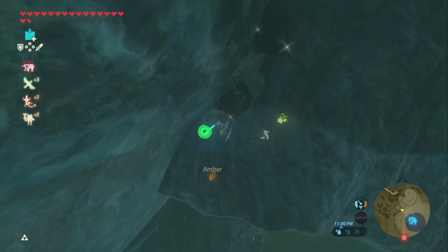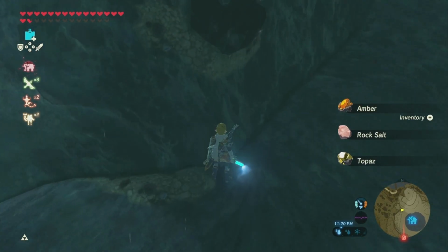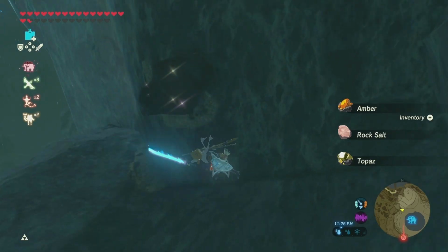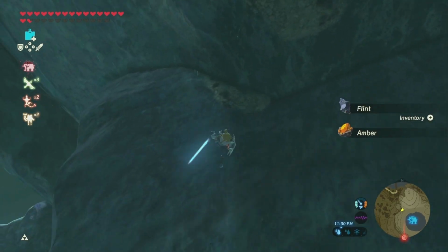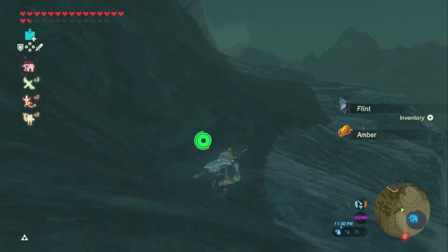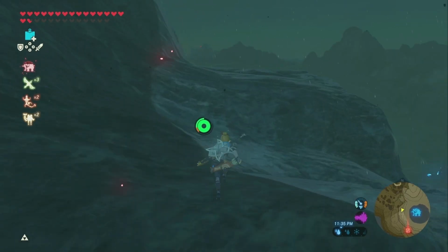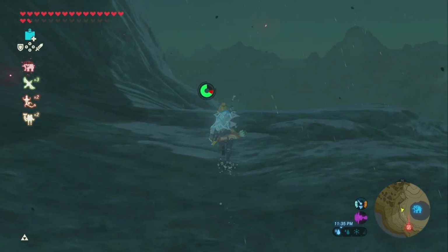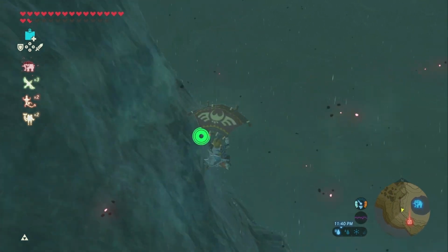Pump. The electrical operated pump is typically a small capacity unit often installed on the return line of the loop. Some are installed on the hot water heater and others are installed under a sink with a bypass valve. Some pumps are set to run continuously, some work off of a timer, while others are operated by an aquastat.